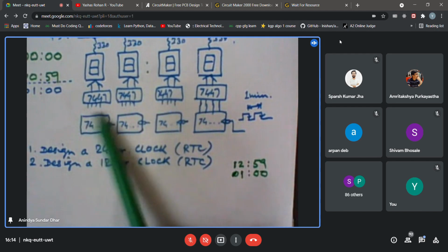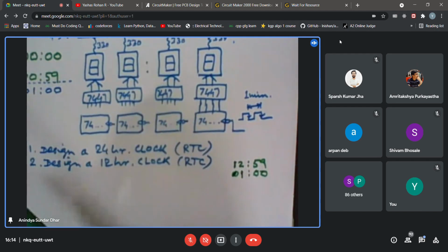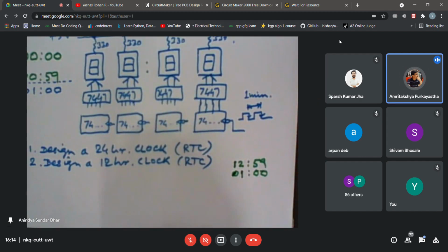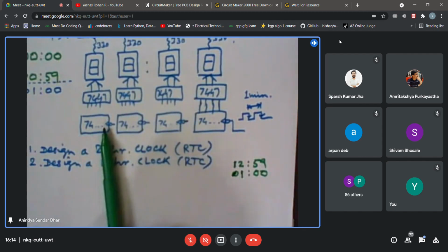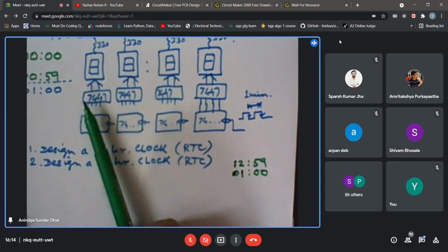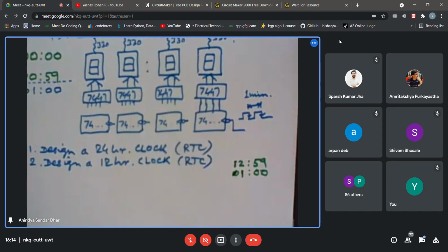Similarly, do I require a full-fledged 7493 or 90? You can just use a simple flip-flop. But anyway, since we are using 7490, maybe only that lone flip-flop you can use right now. But for the 7447 also, you may think whether you really need it, or you can bypass it and do some tricky things over there. Okay, so please check.